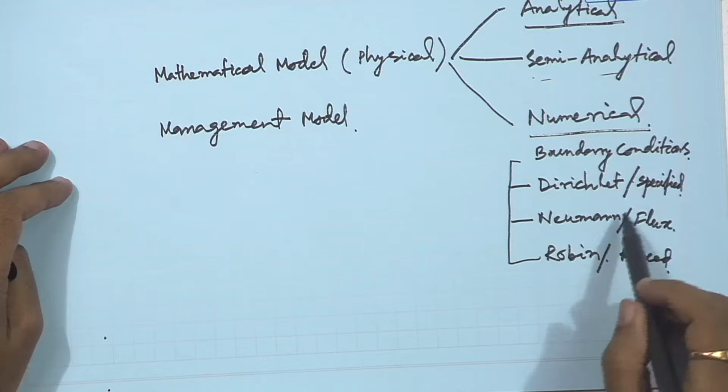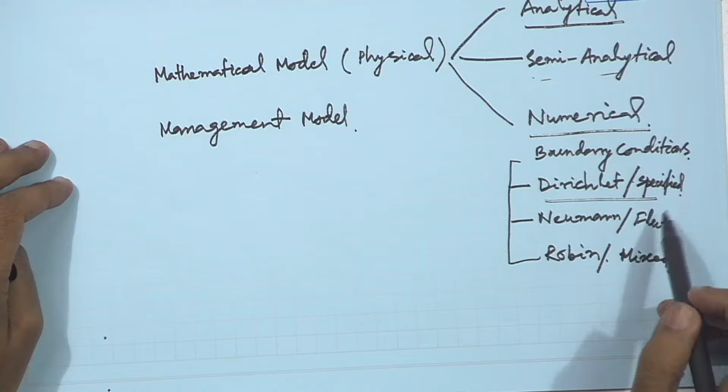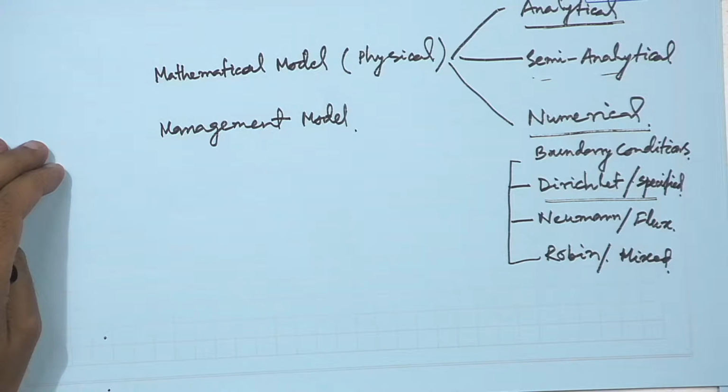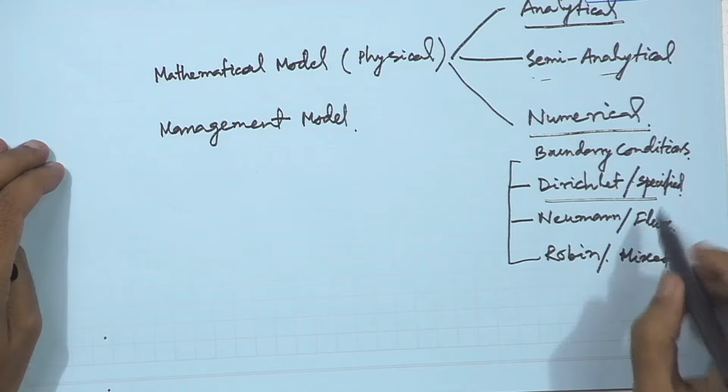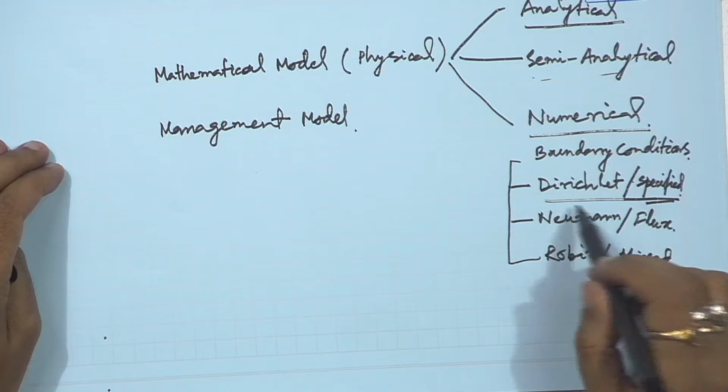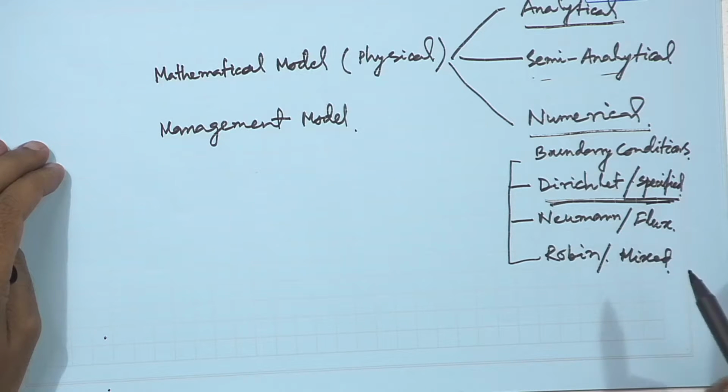So what is the use of this? Let us say you have a river and you know the stage value with time. To solve the groundwater flow model, you can directly specify the head and get the solution.